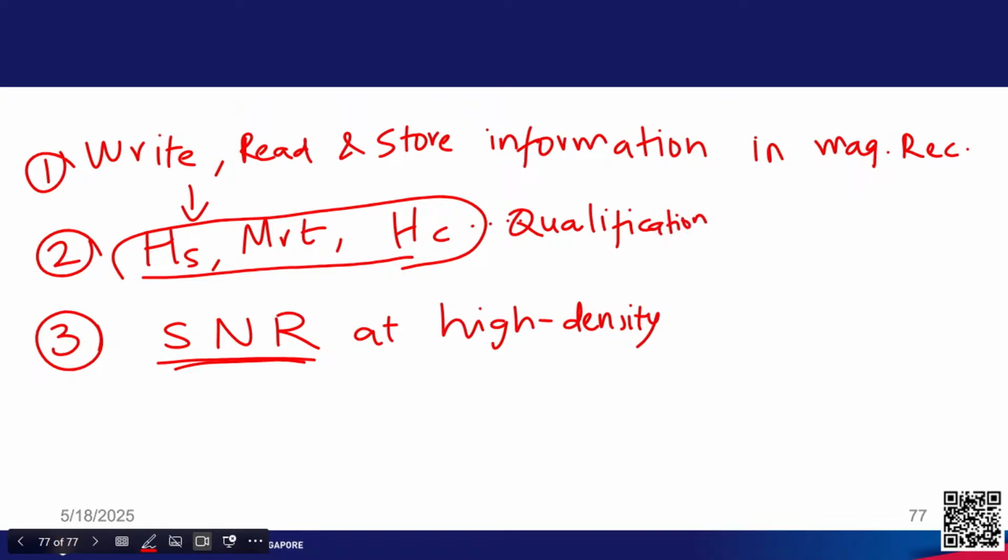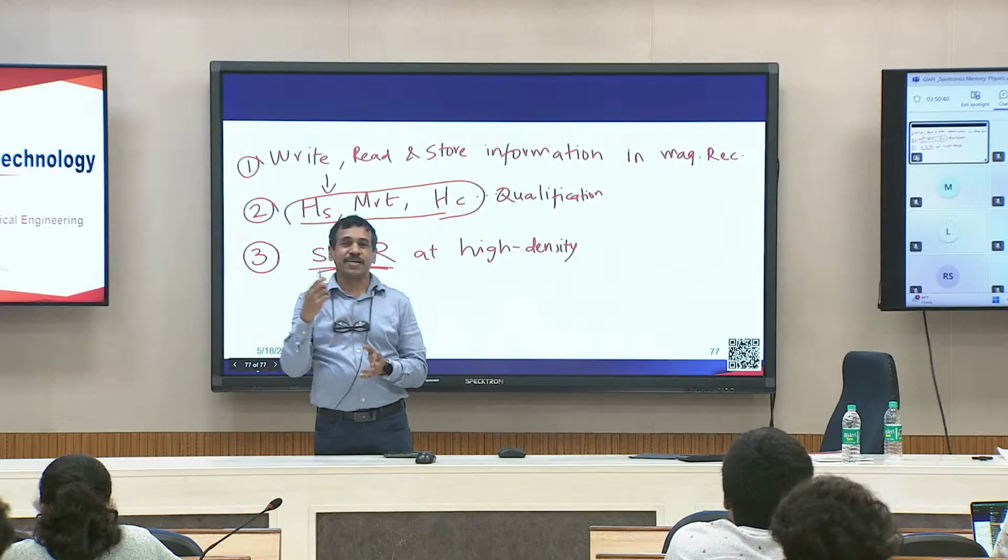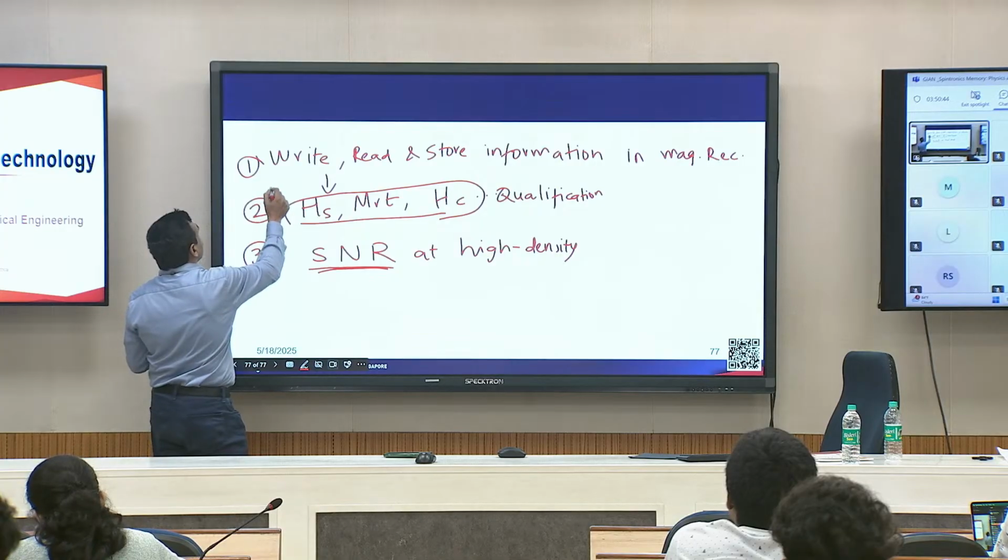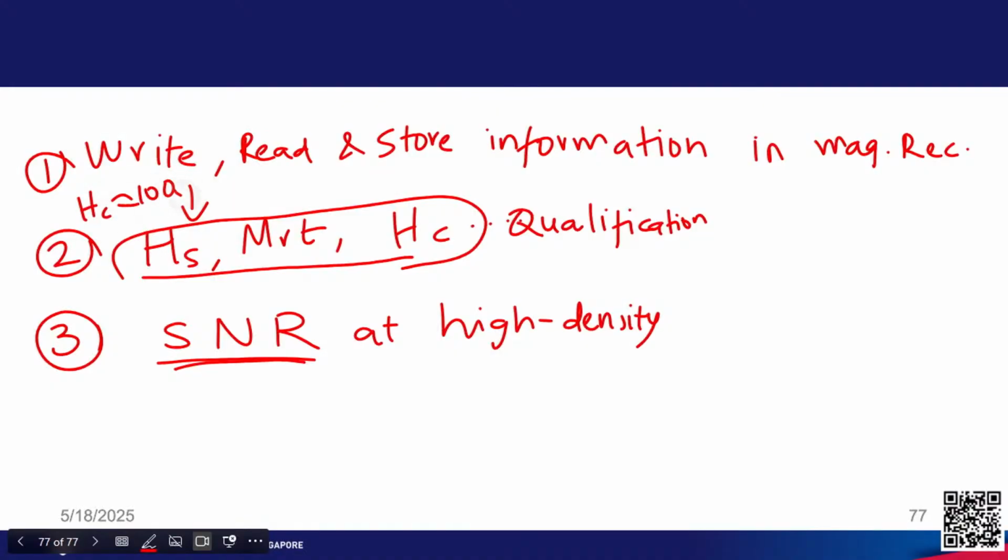To give you some example, right, I see many papers on magnetism. Okay. People will study some magnetic material which may have a coercivity of maybe 10 Oersted, okay, but still they will write in the introduction that magnetic materials are useful for magnetic recording and all those things. Okay. So, when a material has 10 Oersted coercivity, you cannot write that kind of introduction, because 10 Oersted coercivity is totally useless for magnetic recording. Okay. So, we are talking about materials having 6,000 or 10,000 coercivity. Okay. And we are also looking at so many other aspects that determine how a magnetic recording technology will perform. Okay. So, people try to improve this signal to noise ratio, all those things.